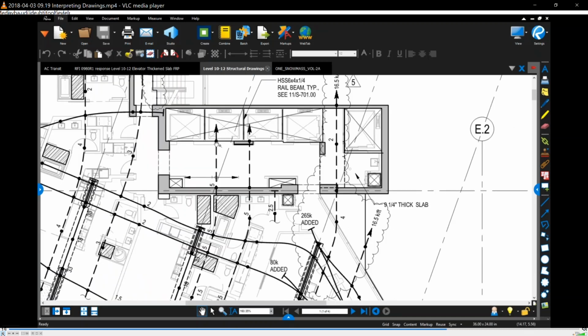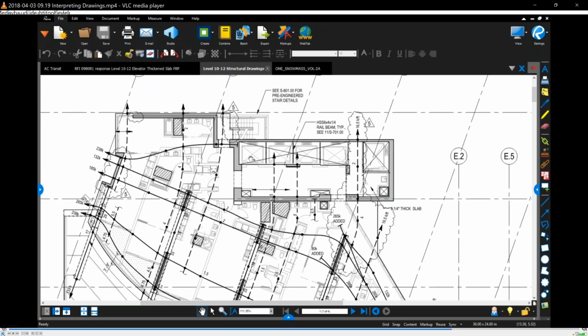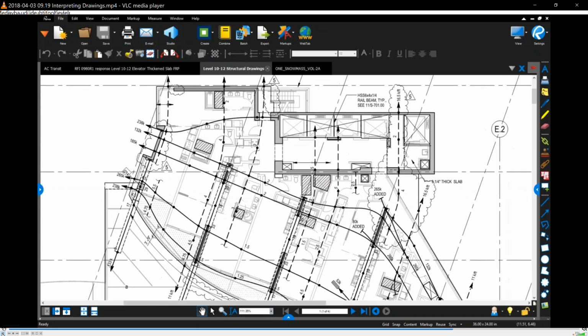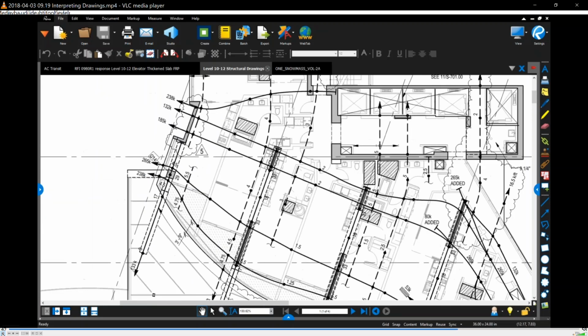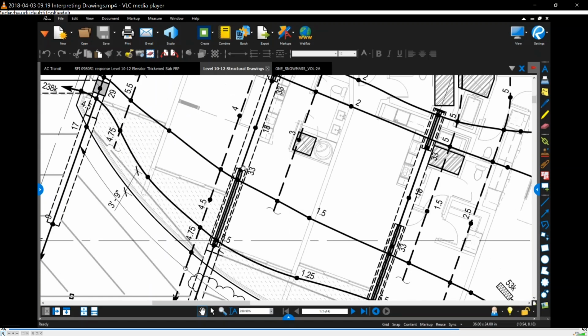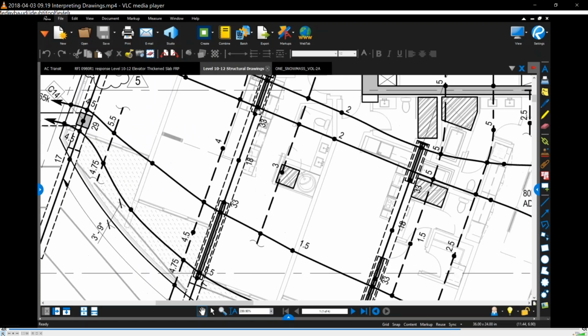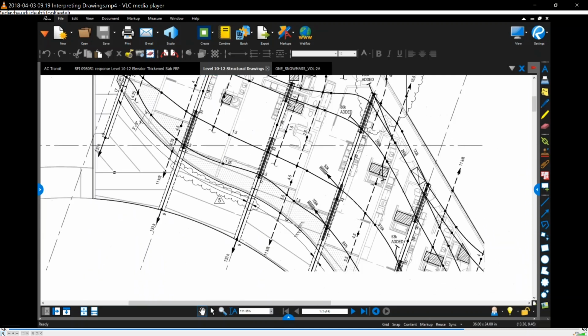These engineers draw their stressing ends extending out beyond the edge of slab, whereas the washer ones you saw before had the arrow right at the edge of slab. A little bit different drawing conventions, but similar idea. Again, these don't call out the units. This is the 4-inch low point for this particular cable, 2-inch low point for the banded direction. This is a 33-inch high point, so this must be in a beam. That's why it's got such a tall high point, or tendon profile there.